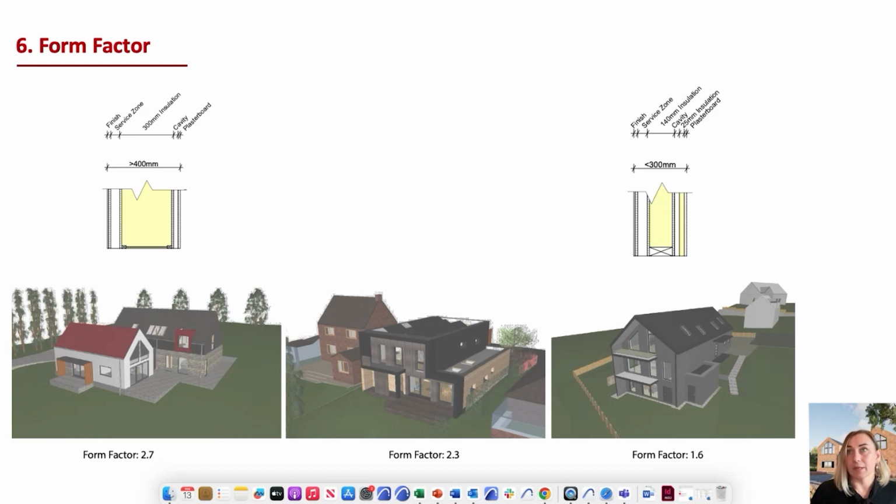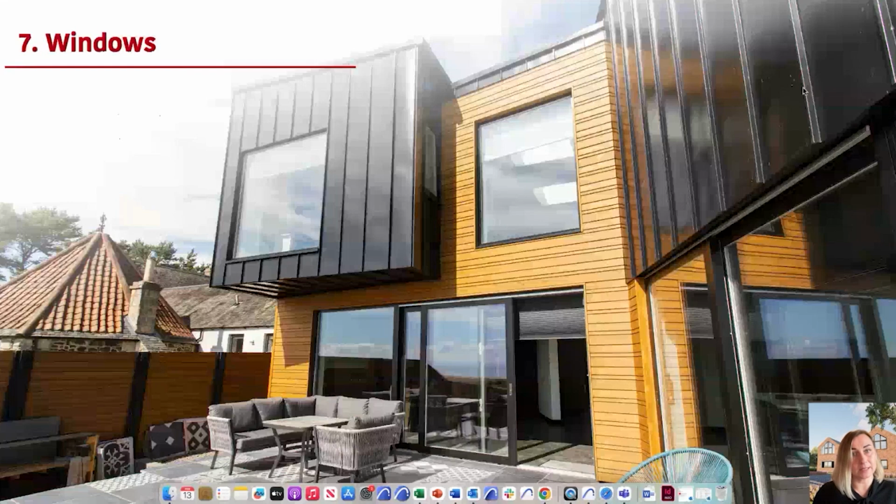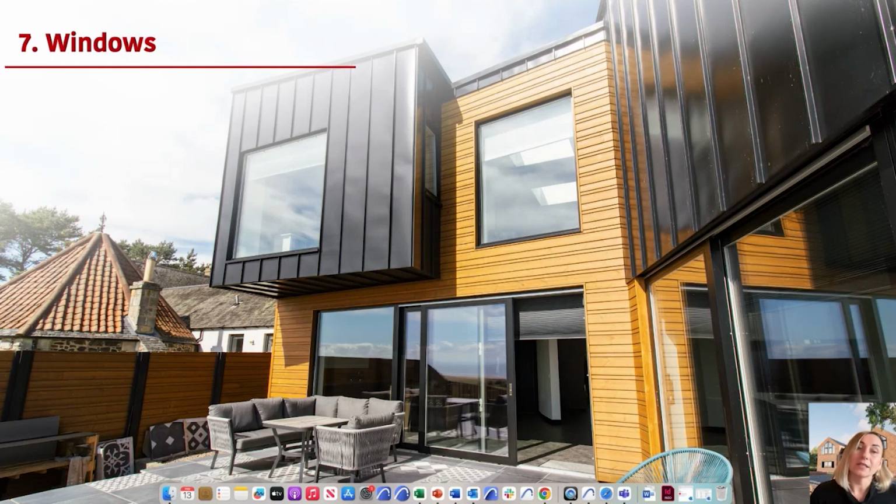And the next aspect, which is quite important as well, is the windows. So the glazed surfaces play an important role in the passive house because they serve as solar collectors, bringing the light and the heat, whilst also providing natural ventilation. So locating the majority of glazed surfaces on the south facade, as we already said, helps in achieving the maximal solar gains, while reducing the ones on the northern facade will help the use of the insulation within your construction build-up